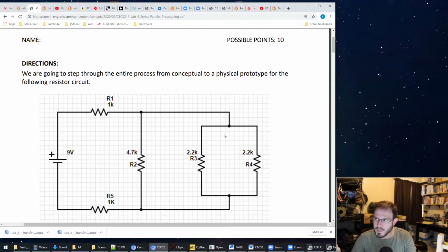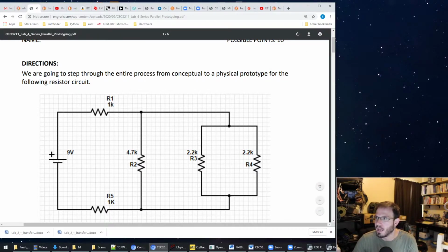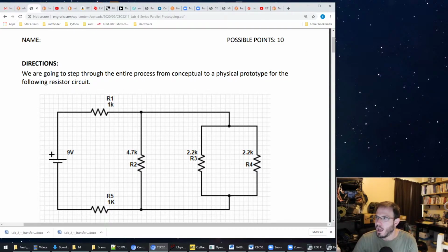Okay, so this was the circuit that we were prototyping. We had this 1K up here, 1K in the bottom. These were in series, and then we had these three resistances, the 4.7K and two 2.2Ks in parallel. And let's also take a look at this 9-volt voltage source that we need to apply to this circuit. Okay, so if I pull up...